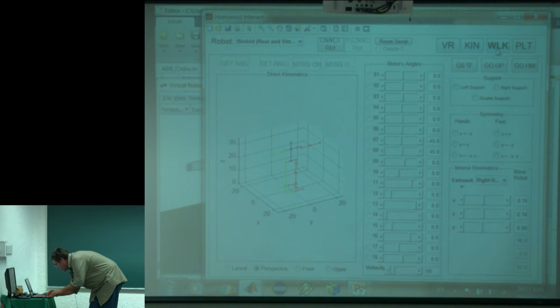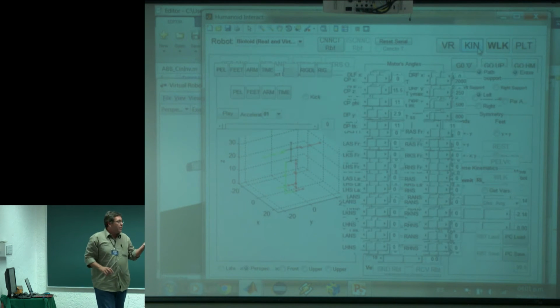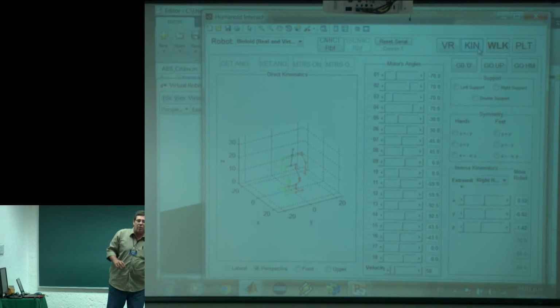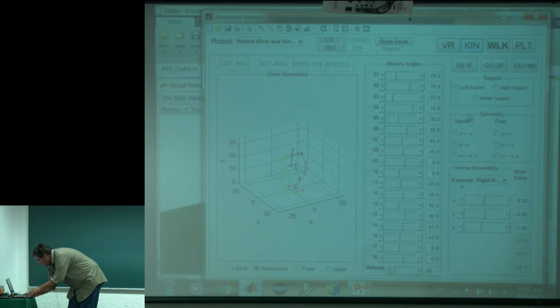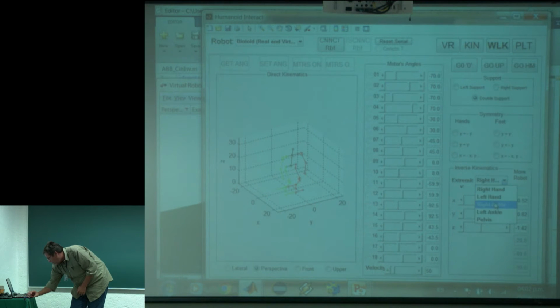Another important thing that we can say about this is that the same configuration is, for example, for HRP2, for Honda humanoid robot, for several robots, it's the same combination of angles. So we can see here that if you set the robot in double support, then you are able to move, for example, the pelvis in vertical direction, toward backwards, forwards, and in lateral way, with the same orientation of the pelvis.